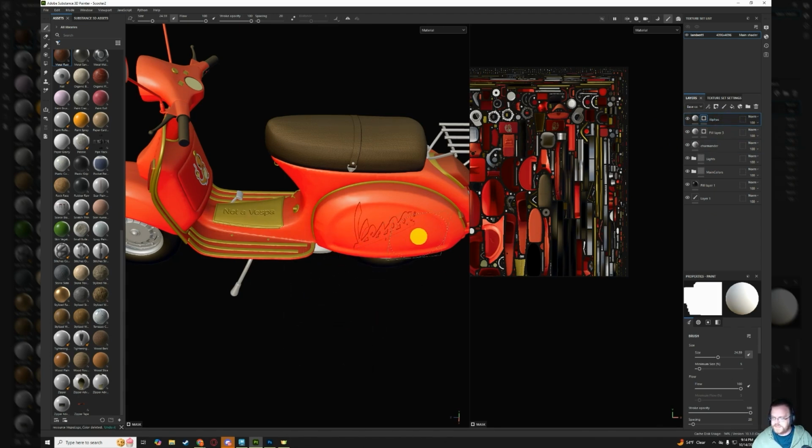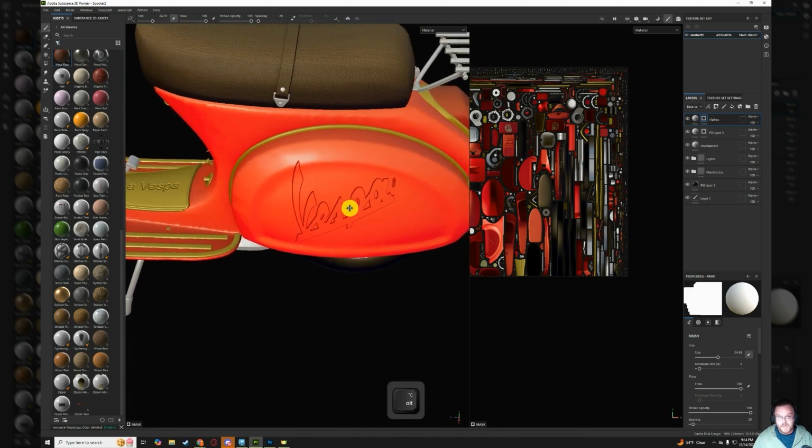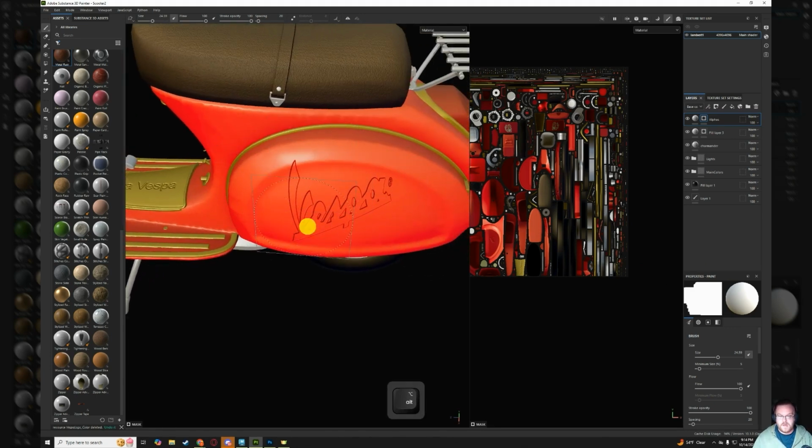So I'm going to talk about anchor points. Anchor points are going to tell Substance that normally when you paint over things like height alphas and stuff like that, Substance doesn't know to calculate the data from that height map in what it's painting. So if you give it an anchor point, then Substance Painter will know to take that data and calculate it when it paints on top of it.